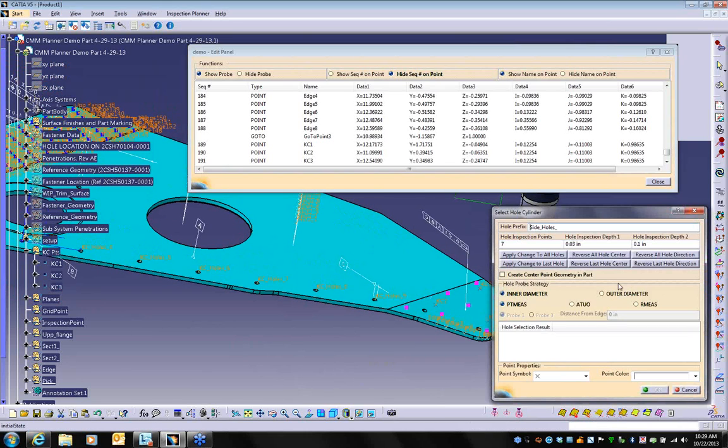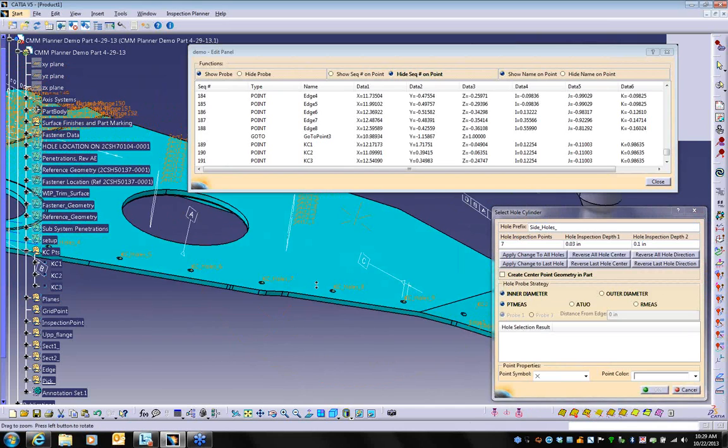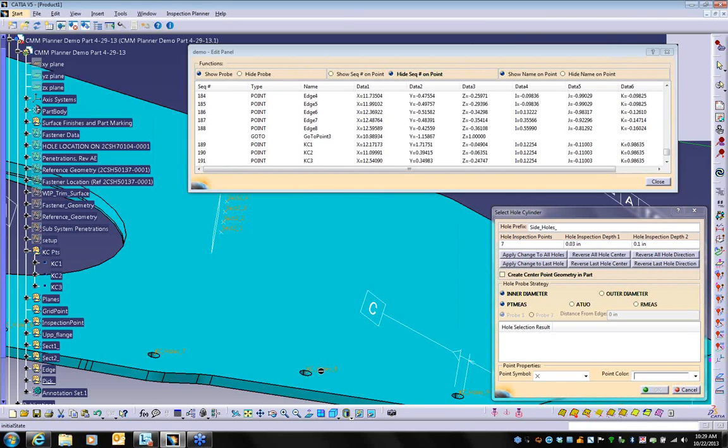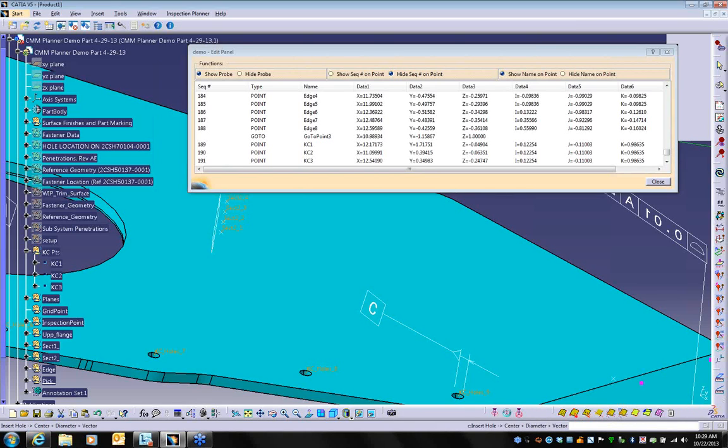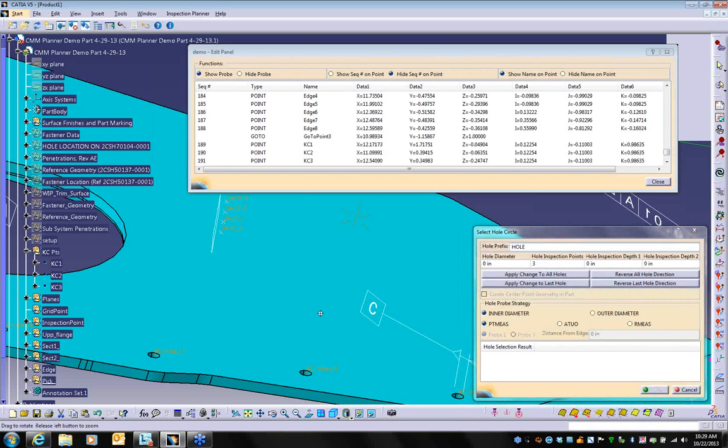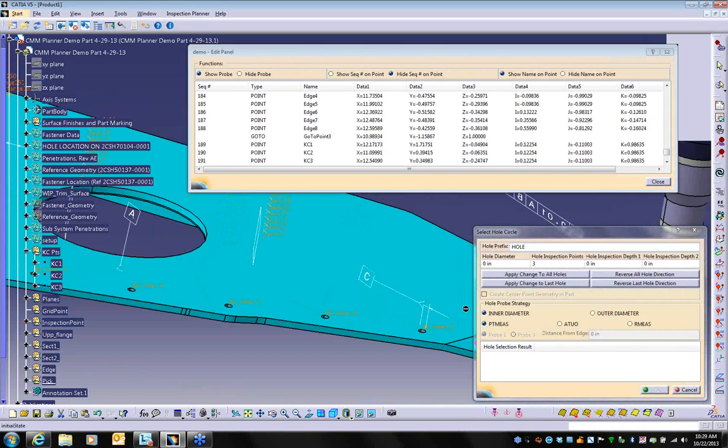This is our 5-axis holes. Right now what I demonstrated was 2D holes that were on a flat surface. If they're 5-axis holes that are going through a contour, you would use this icon. If it's like the old E4 days where the OEM gave you a point and a line, we have a pilot hole. This icon just prompts you to pick a point and a line.